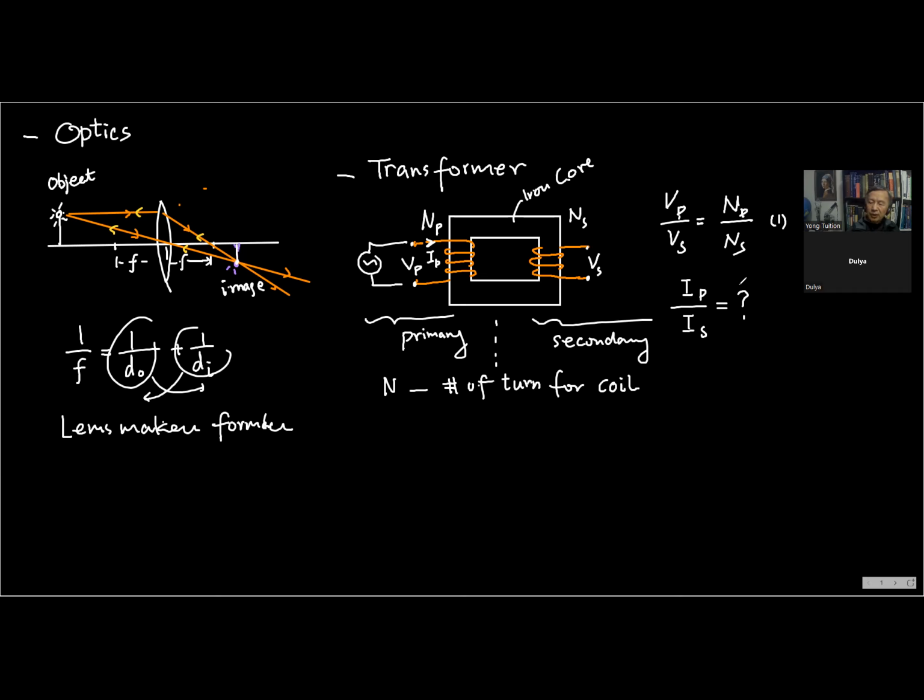So I will show you how to obtain the second formula first, all right? How do we prove this formula? We have two assumptions. To derive this formula, we assume, as in solving this question in physics, that the power doesn't change. Can you see? P primary is equal to P secondary. Or in other words, no leakage, no energy disappears, okay? No leakage.